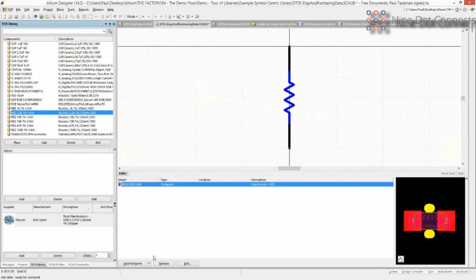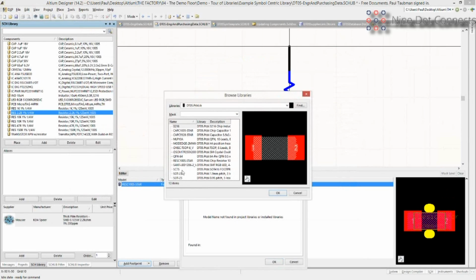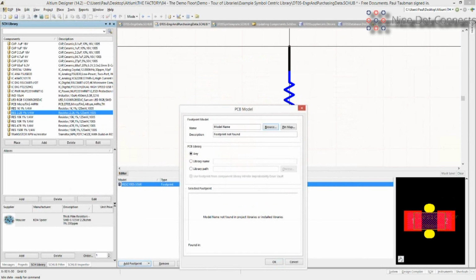Because in this case here, yeah, I've got this set up. But if I go over to my footprint library, and I click on Add Footprint, and I go over here to look for it, and it should find it here pretty quick, I want to make sure I can read these things very easily. It's one thing to have a picture, which is certainly good, but what does this associate itself to? It actually took me over 30 minutes to figure out that this mod edge here was a custom part that Altium used for its DT05 project, because I couldn't find it anywhere when I was trying to look in the supplier searches. So it's important that you come up with a good naming convention. But more importantly, someone's already done that for you, and that's the IPC.